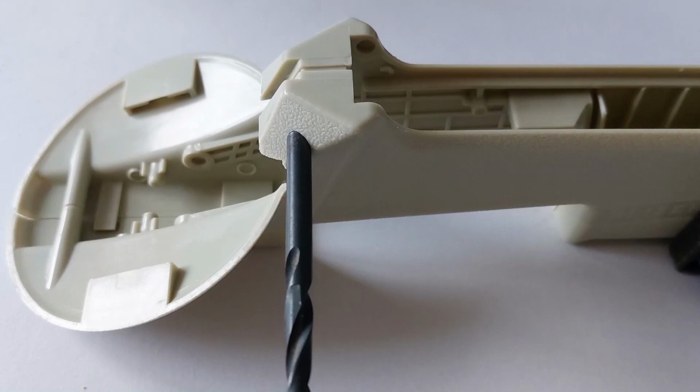For the hole position, there is a trick I've not seen others using, which is to plug the hole, leaving some of the plug exposed. The exposed part scans easily. And you could use a dowel, or if it's a screw hole, you can put the screw back in. Drill bits are also quite handy, as are rubber bungs and cocktail sticks. The rule is that if you can see it, you can scan it. And obviously, you don't want to use a loose-fitting plug.